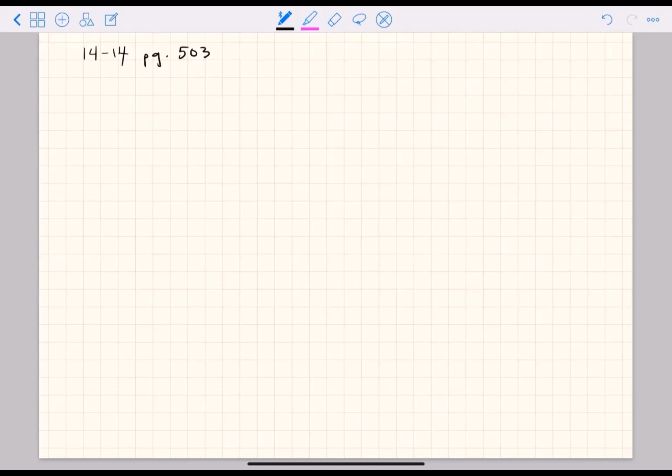But we're already starting with a displacement, and that displacement is from its uncompressed or free state. So here we're starting with already some compression, and then we're compressing it even further. So it's a little bit more complicated than just plugging numbers into that equation. So I'll show you what I'm talking about.